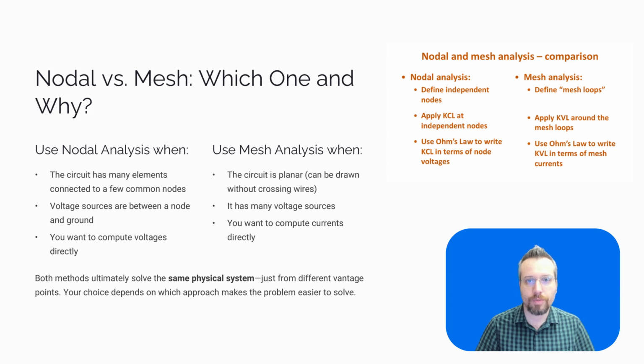But how do we decide which method we have to use? We use nodal analysis when we have fewer nodes or the circuit has many resistors connected to ground, and the main goal is to solve for voltages. We use mesh analysis when we have a planar circuit and loops are clearer than nodes, or we have many voltage sources.